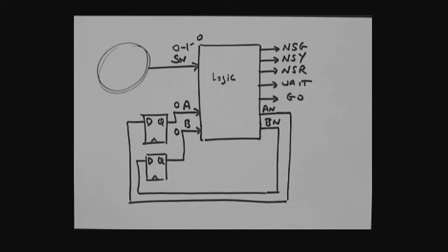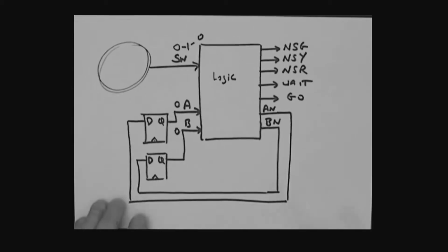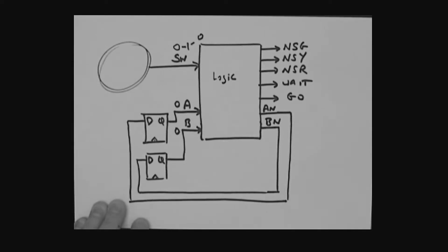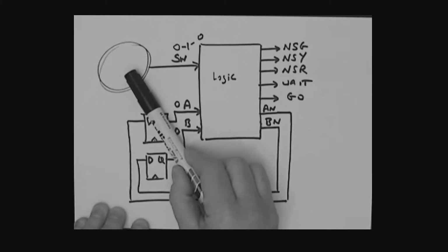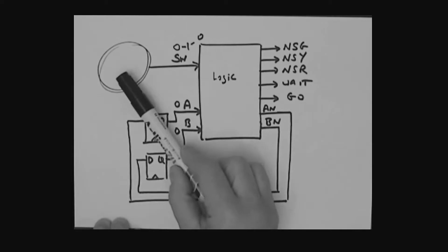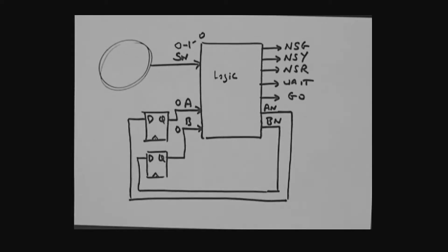Okay, look, in the last part we were really addressing the switch issue. This is the crossing switch. And remember, we were talking about a situation where somebody might momentarily press this switch. We wanted to capture that, we wanted to latch that in, okay? And so we looked at using an SR latch for that purpose. So we'll just recap that very briefly.